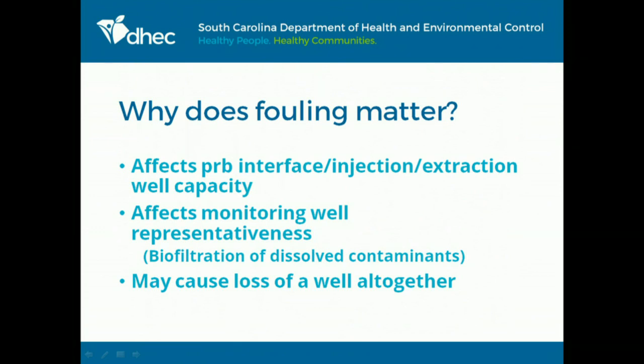And the really big thing about fouling, and this is historical, that everyone knows, is you can actually lose an extraction well. And extraction wells can be pretty expensive to replace. I have a site where they're having to replace one, and it's a $30,000 replacement. You can do treatment for fouling, but you have to be aggressive about it. You have to look for it. You have to continue to treat the wells for fouling.